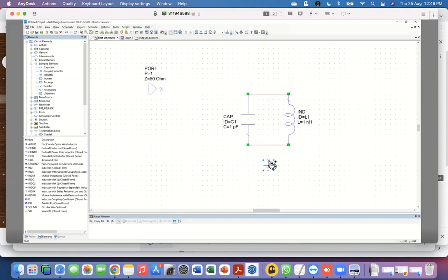Now you bring this and connect the ground. So there has to be always a ground terminal. So this ground object, I got it from here at the top. Okay, so you can bring it from here like that. And this is something you have to always remember, that there's always going to be a ground reference. And then the last thing is this thing called port, which again is here. So let me delete this and bring that again.